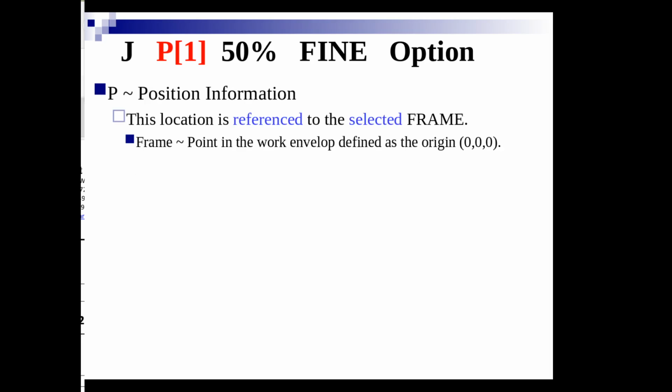One thing to say about these points or positions is the fact that they are stored. They can either be stored as the joints. So if you have a 6-axis robot, you just store the angle of each joint, and that's where you're going to go to. Or you can store the frame. So if you're in frame mode, it'll actually have a user frame and that tool frame with that tool center point, both are stored as part of the point. Okay.